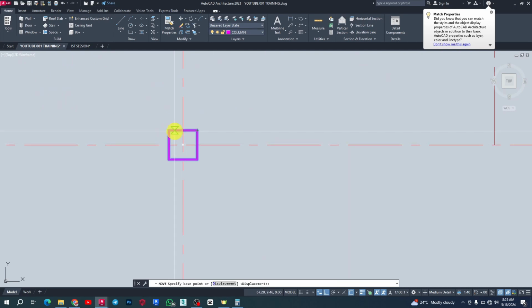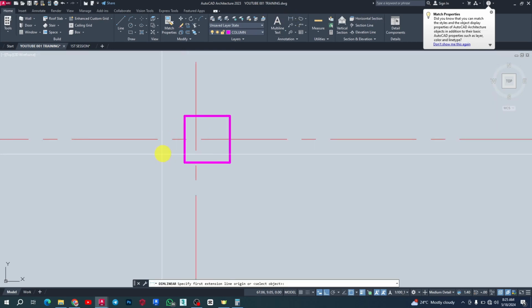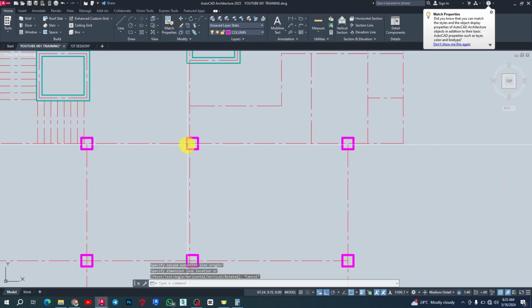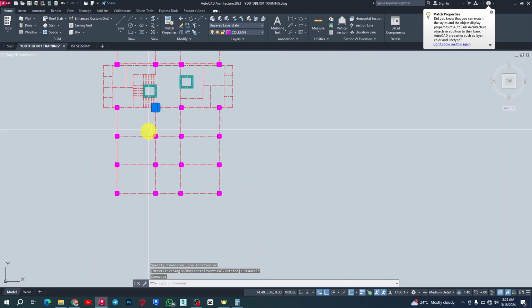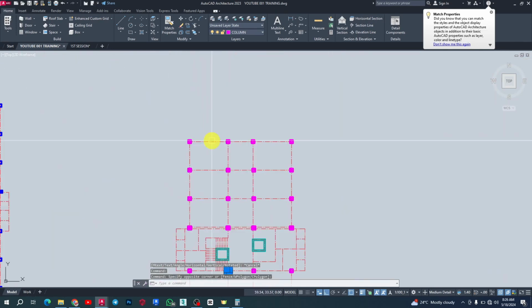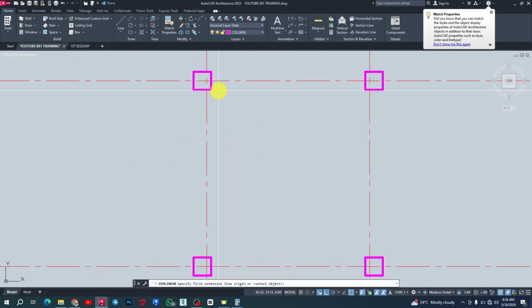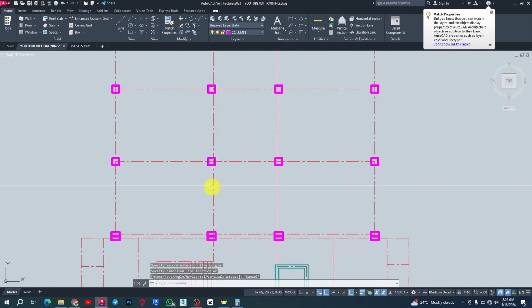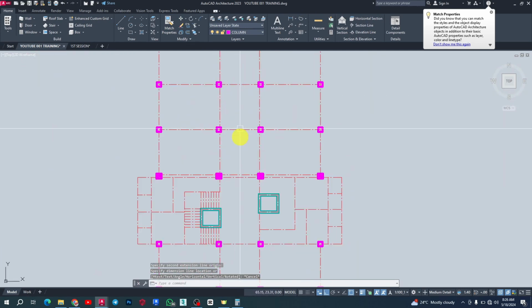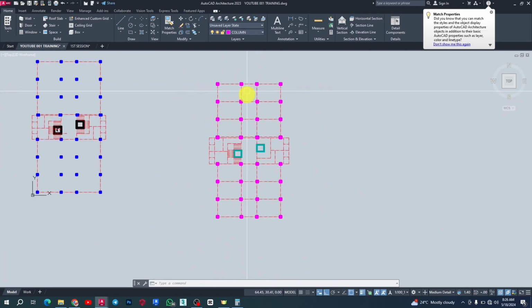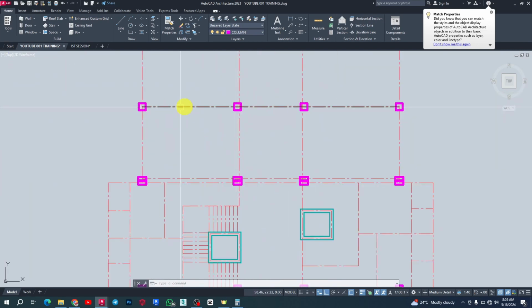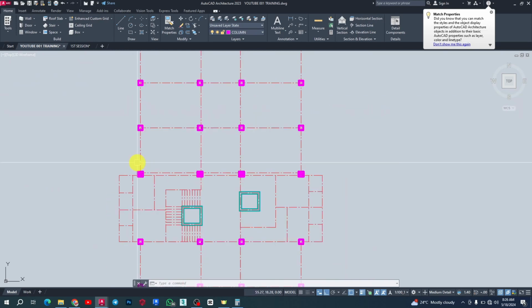So what distance am I going to subtract? I have 250 here, so I'm going to take 0.125. So I have to have again 0.125 here. So that is it. It works like that. Okay, so I'm going to take this one again, shift it, and then take these two and extend 0.125, 0.125. That is it, right? So I'll have my beam flushing directly on the face of this column, and then I have no column showing from inside from this hallway, this circulation area, right? And also giving priority to the maximum moment that will be generated from this longer span. I think that will work well.